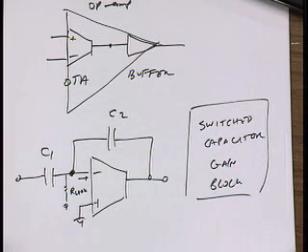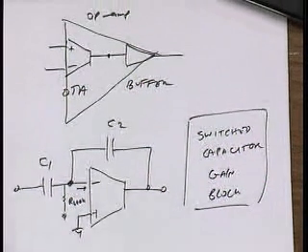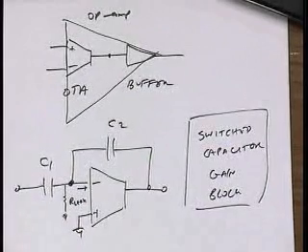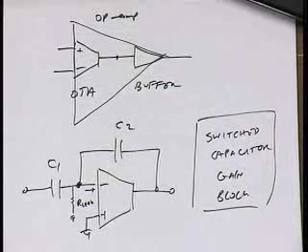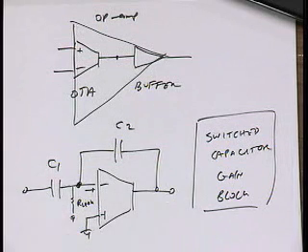If you're building today, if you build analog circuits, inevitably they sit in front of some digital circuits, right? And so you know that at some clock rate with some resolution, the signal is going to get digitized. So that kind of gives you the freedom to also run your analog circuits in discrete time. There's no reason why you have to run your analog circuits in continuous time. So what can you do in discrete time?